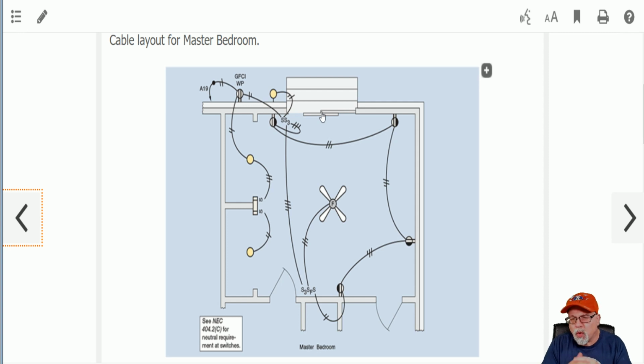And you as an electrician want to space things out as neat as possible, right? So in this case, I'm going to go probably the maximum 6 feet. And then I'm going to go the maximum 12 feet. And if my receptacle at that maximum 12 feet still is putting a receptacle within 6 feet of this opening, then I'm okay.